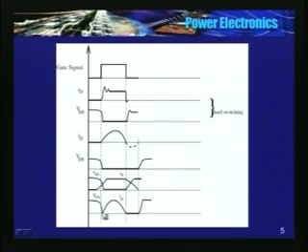In other words, the switching losses are practically eliminated. And this current rise is an LC circuit, some sort of a resonant current. So there is a significant reduction in the di/dt also here. You compare these two. This happens both ways, while turn on as well as while turn off.